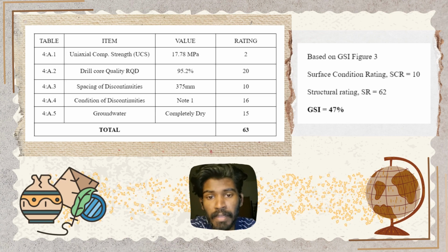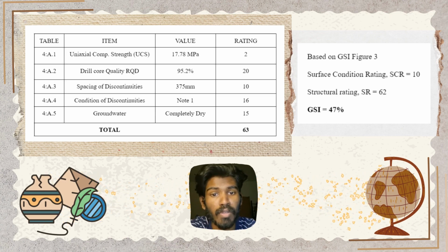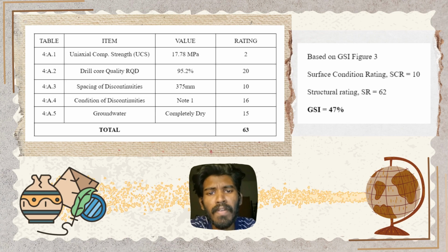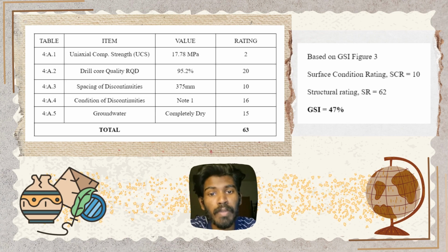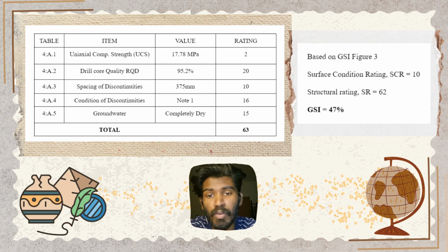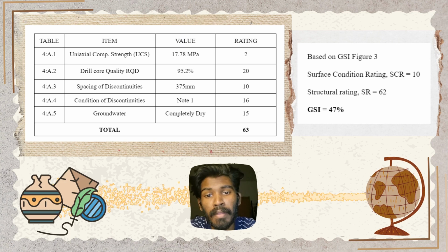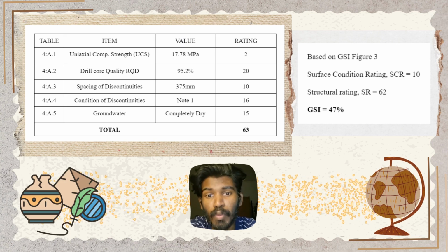And the second thing is drill core quality, which is called RQD. We got 95.2% of it, which shows it has a good quality of hard rock. And the rating we have given is 20 for it.